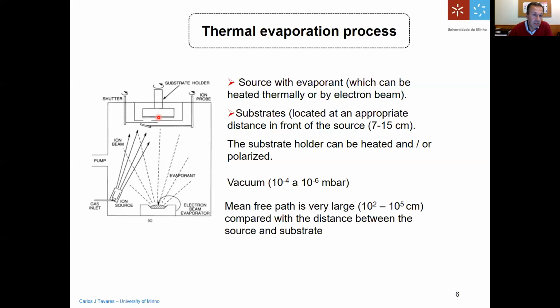So, as I mentioned, atoms will have some mobility to cover the surface, but they will nucleate on defects that are on the surface, for example, on impurities, on protrusions, or discontinuities on the sample surface. And if you impinge these very high energetic argon ions, they will create some defects here on the surface. And these atoms, when they reach there, they will grab this surface. It's just like if you're riding a bus and the bus is empty and it accelerates very fast, you try to hold on to something, otherwise you'll fall. And you want to stay in the same place. So these atoms will also want to grab a position so they can start nucleating the growing film.